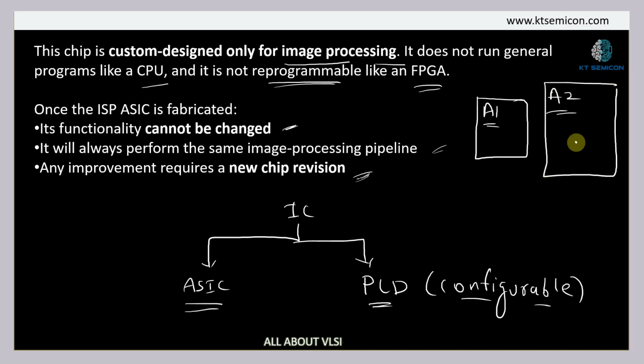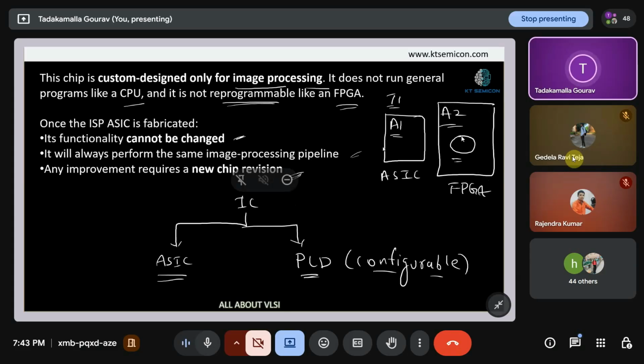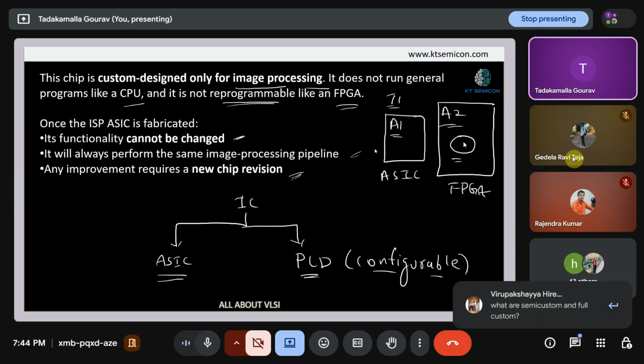For a task T1 or any application, if we use an ASIC, we use this much area. But using an FPGA, we are going to occupy this area, but in this area, we are going to utilize only this much. We can also reduce the area needed in FPGA by using some techniques. But the overall area available will be this much, while the utilization will be this. Okay.